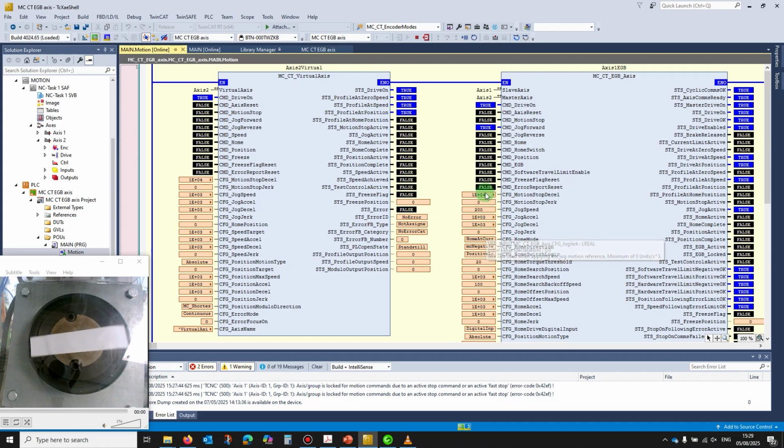Okay. The only reference where that's not true is actually for motion stop, because this uses MC stop and you can't change the rates or execute another instance of MC stop whilst you're in the process of stopping. So that's a restriction of PLC open.